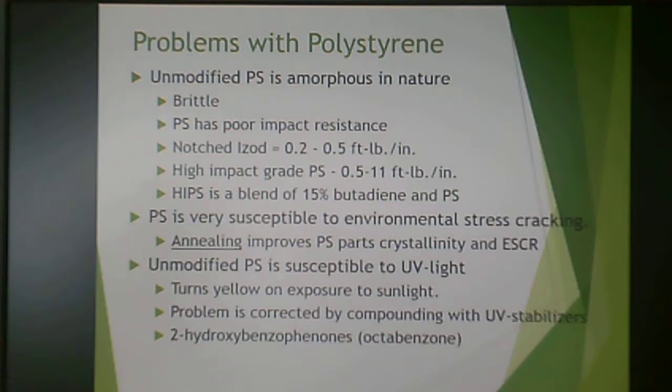Polystyrene is very susceptible to environmental stress cracking as well. One way to improve that is to anneal the parts after processing, and that enhances a little bit of the crystallinity in the polystyrene part and gives you some environmental stress cracking resistance.